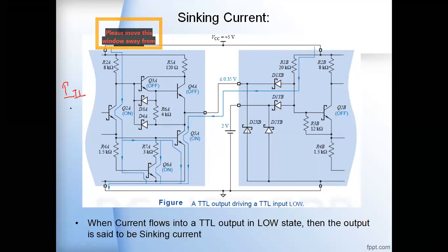So when we see this parameter IIL maximum, when the output of the TTL gate is in the low state, the current flows out of the TTL input.